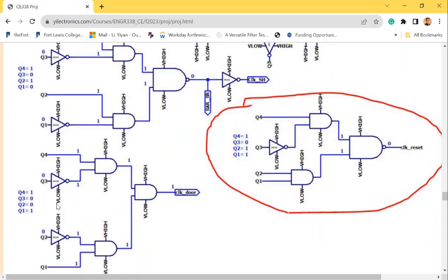It's very interesting. So we actually started from here. We did not start from the conversion, but we start from when we finish the conversion, assuming it's done, right? And then we start the next. So the 9th cycle will kick it out, and the 10th cycle will reset it, and at the same time do the sample and hold.